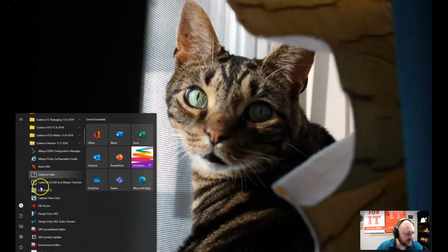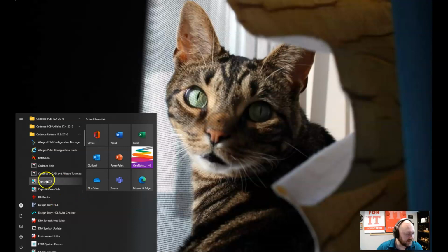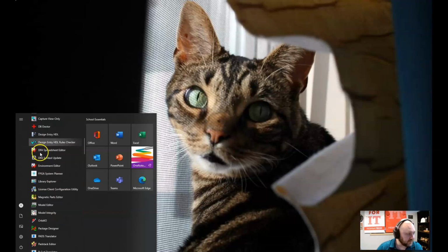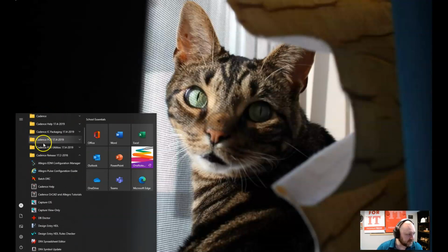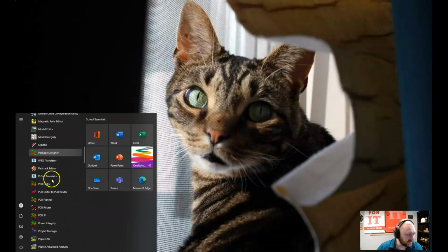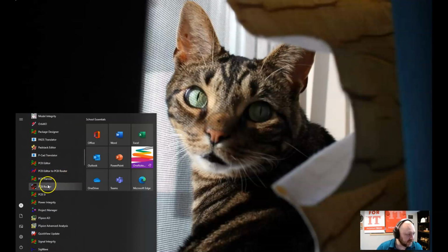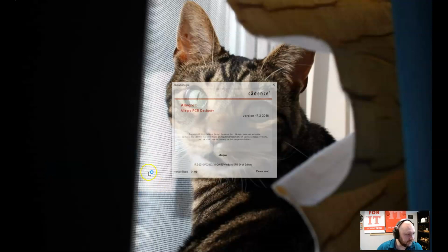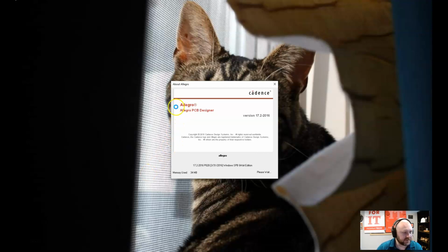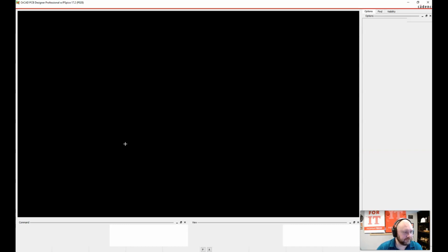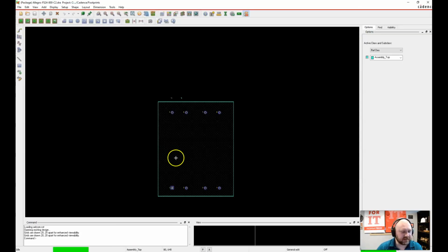I'm going to go ahead and get the footprint editor. Now we have this capture. Technically, yours might look different. It might be under Allegro, as opposed to mine here where all things are just listed under here. You might have under Cadence an Allegro directory listed. But basically, we're looking for the PCB editor. And you can even say it's Allegro that's being launched here. And if it says something besides Allegro, as long as it's the PCB editor, that's what matters.